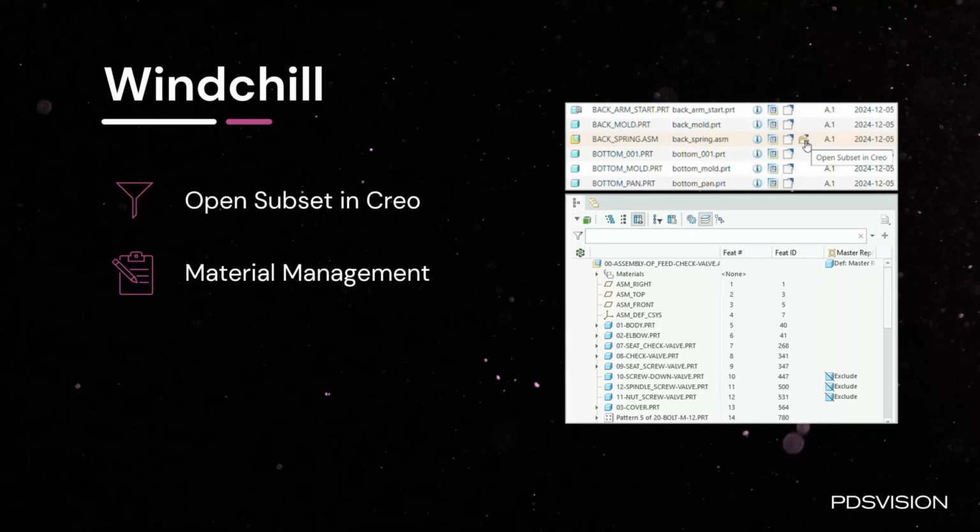This functionality is available outside of Windchill. If you open an assembly when you're not connected to Windchill, you always have that option right next to open in the open dialog box with the drop down, and you can open a subset. What that enables you to do is get the tree structure of that model and pick and choose what assembly options or components you want from that assembly and just open those. That functionality has now come to Windchill.